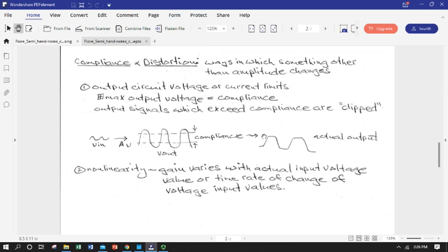So what we get is this chopped or clipped waveform that is very reminiscent of what you would see with a diode clipper. So instead of coming up and having a full sinusoidal signal down, we've whacked the top and bottom off, and this may or may not be symmetric. If we are operating all the way over at one end or the other of our DC load line, we'll actually chop off the entire top or bottom half of our output waveform.